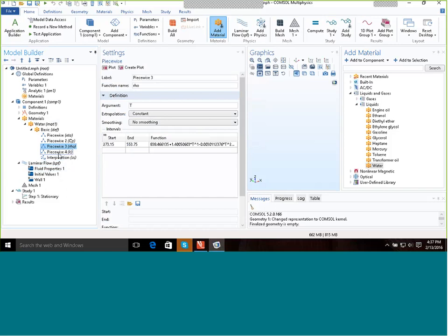And the same for these other things, like heat capacity. We're not going to use heat capacity. I guess one that we are going to use is eta, the kinematic viscosity. So let's click on that. And you can see it uses these two functions in two different temperature ranges. And again, you can see they're functions of temperature. So the physical property database is kind of convenient, because otherwise we have to figure out what the viscosity is or the density. But now we've got this in there, so we don't have to worry about it. If we need any physical properties, we've got them already entered.